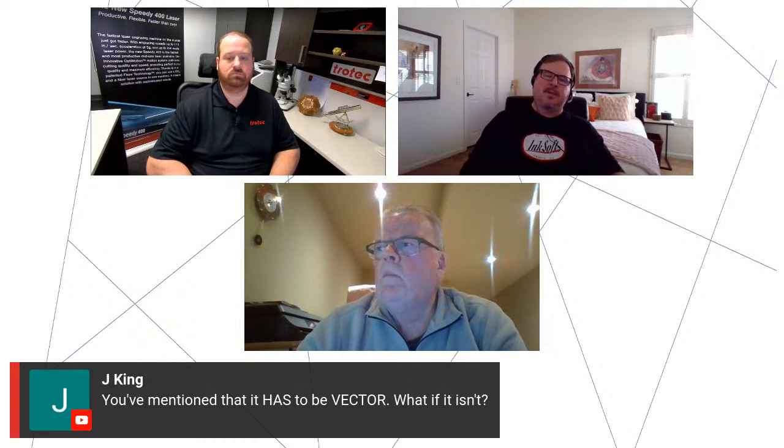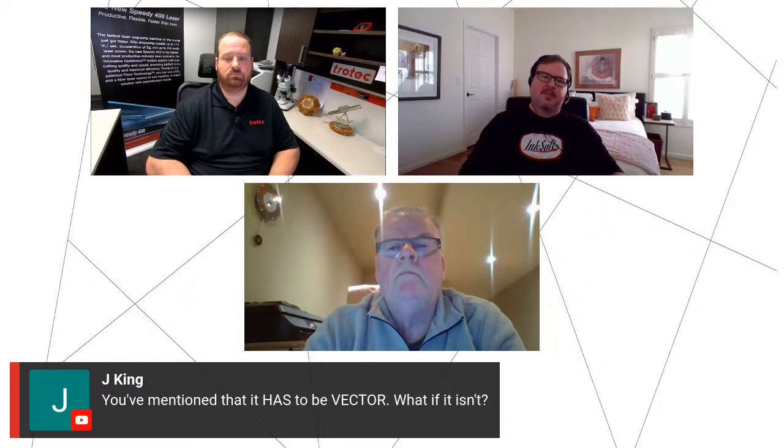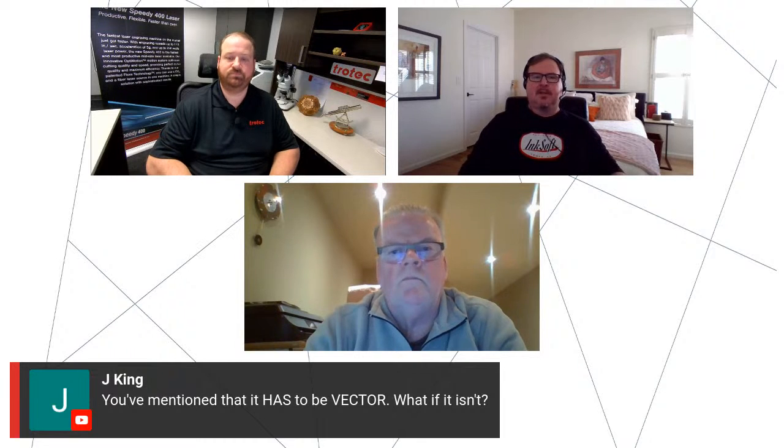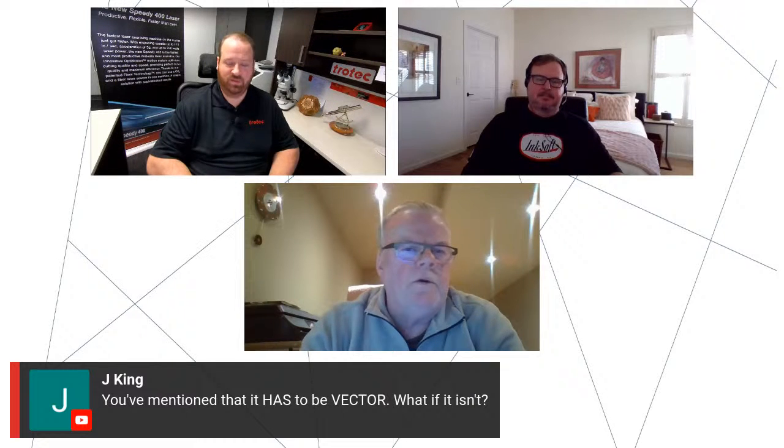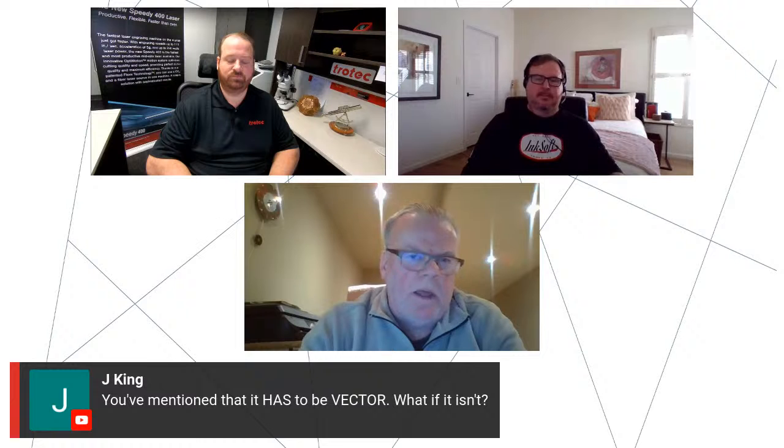If you select a bitmap, you can go in there and adjust the contrast and the brightness to create more of a clear distinction between the dark parts of the graphic and the light parts, so that you can either change the color mode to black and white, or you can utilize the technique that Roger just explained. And I found that super duper handy. That's one of my favorite CorelDRAW features. And fairly quick.